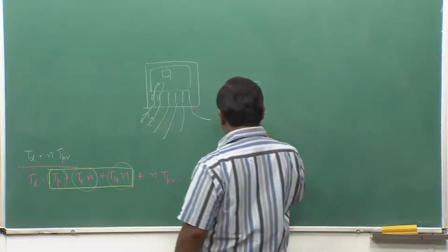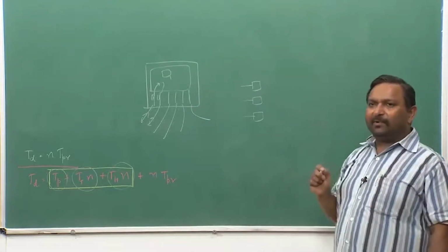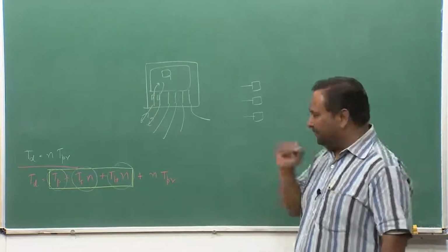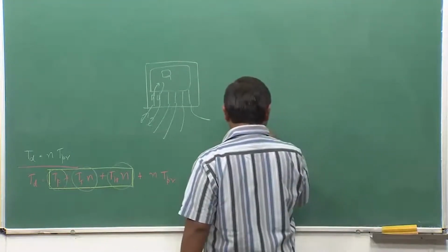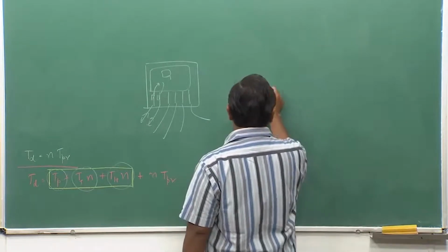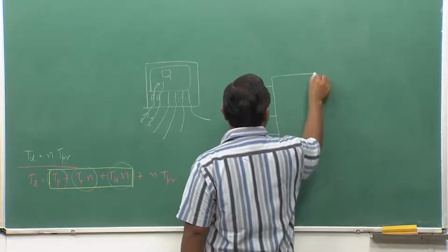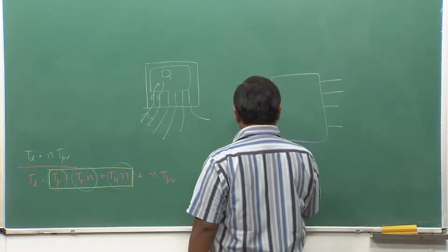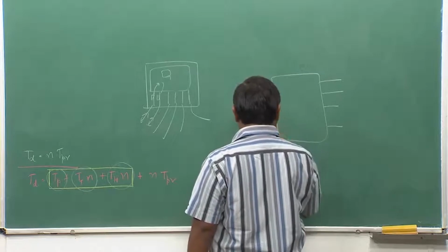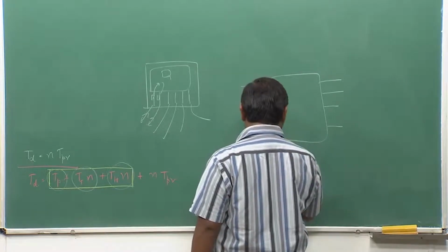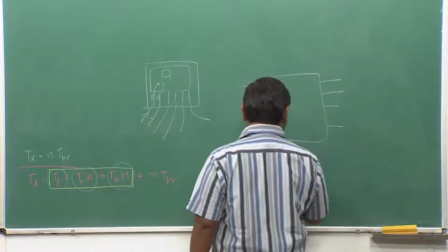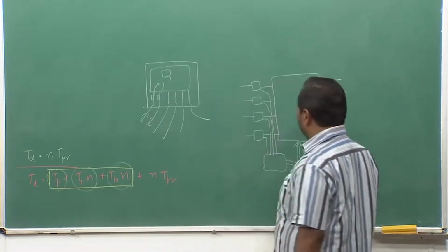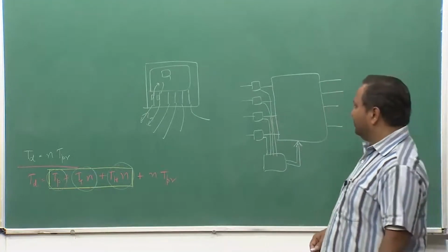Now these interface boards also have another important function, so that I can handle variable length packets. I will come to that. So I am just drawing a 4x4, these are interface boards. This is a crossbar, and I will have one control line through which the controller will get all the header information, and then it will exert row and column control on this crossbar to set up the connections.